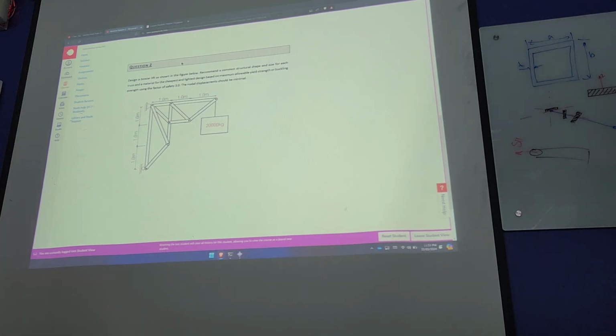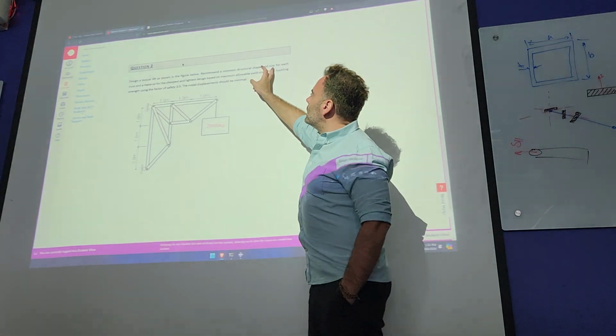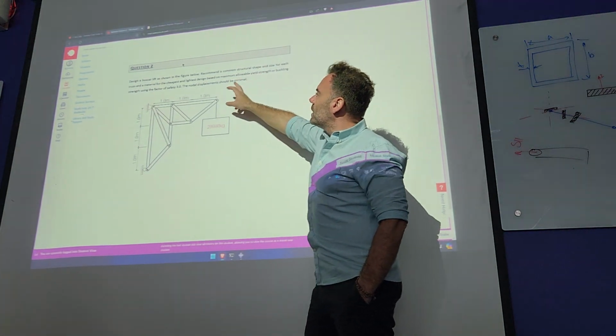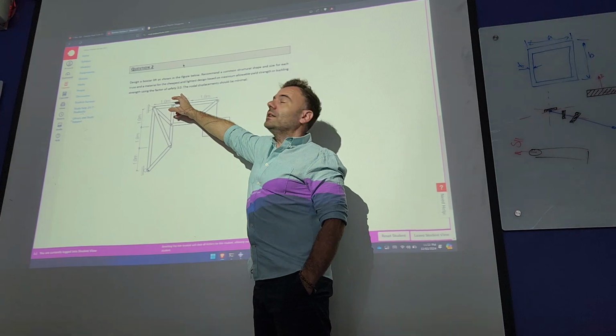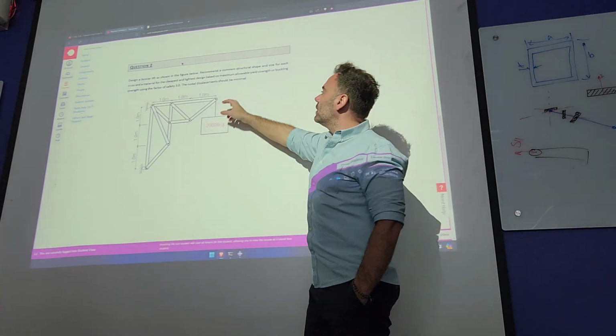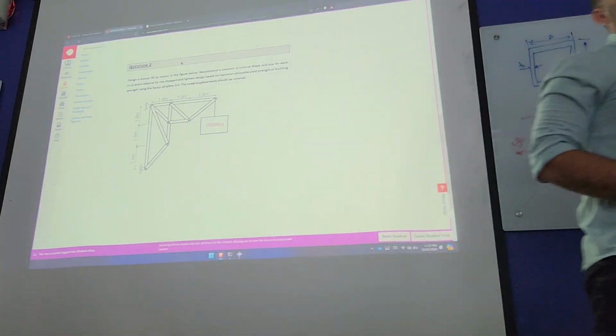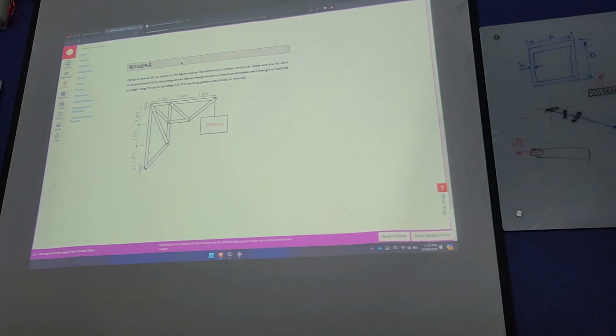It doesn't really matter which way you go. Constraints are that the minimum is below your yield stress by a factor of 3, which means 1/3 of your yield, and there should be no displacement. Yeah? So it's basically trial and error, trial and error.